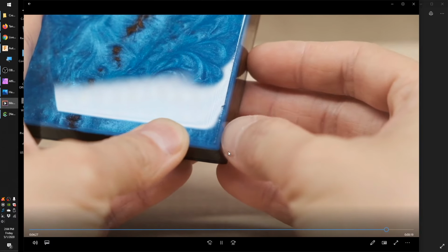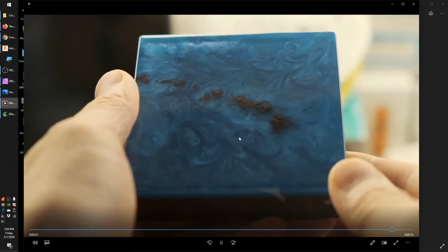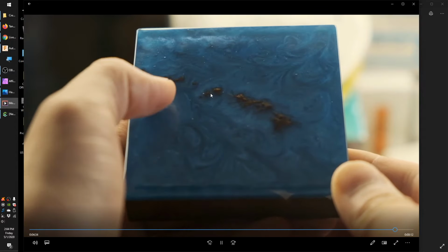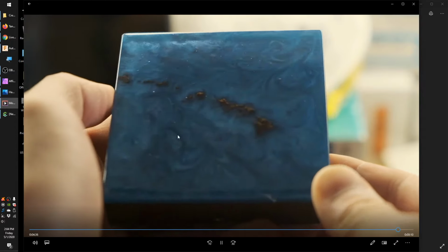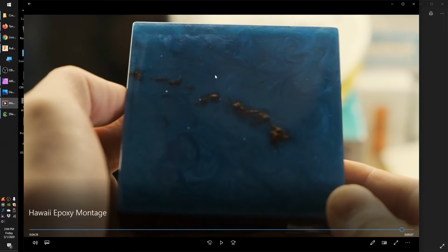And then also around the edges, I didn't show it, but I need to do a little better sanding because my adhesion wasn't super great. And then there were actually some air bubbles that I didn't notice when I was first pouring this because the lighting in my enclosure is super uniform. It's coming down from both sides. And here I just have a light off to one edge, so you get a lot of edge reflection off the bubbles.